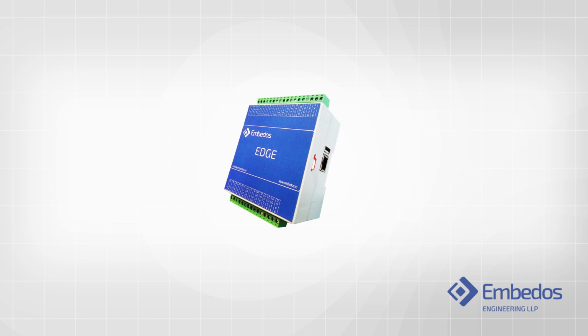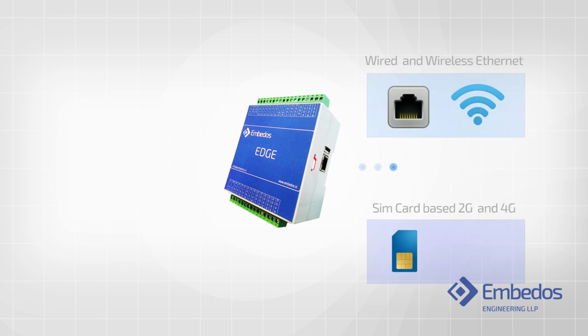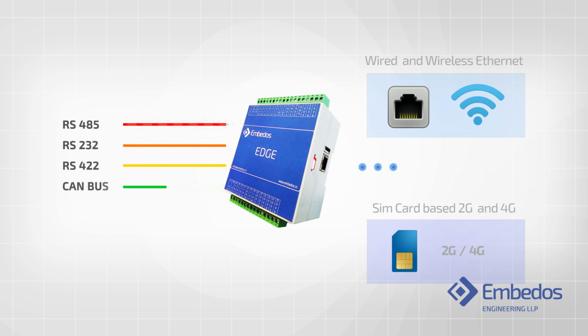The Edge device can be connected to the Internet through wired and wireless Ethernet, as well as wireless SIM card-based 2G and 4G connectivity. Field device hardware interface options include the following: RS-485, RS-232, RS-422, CAN bus, Ethernet.